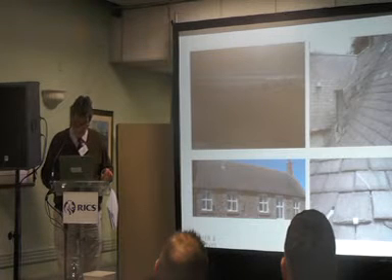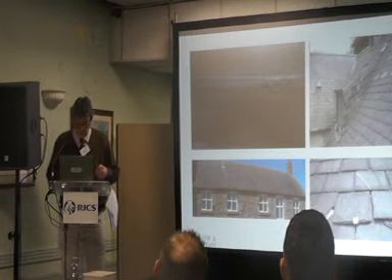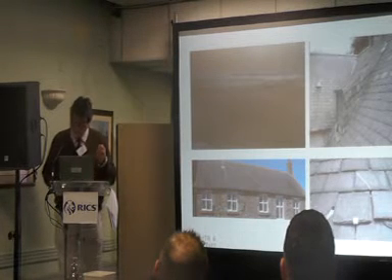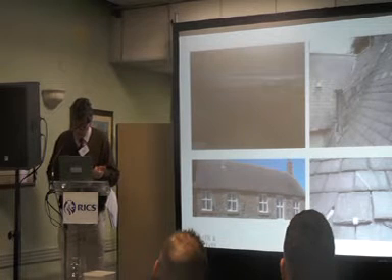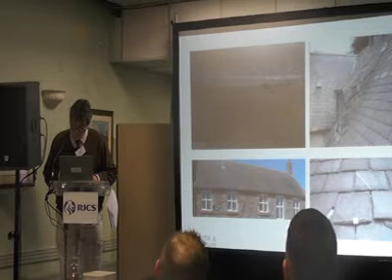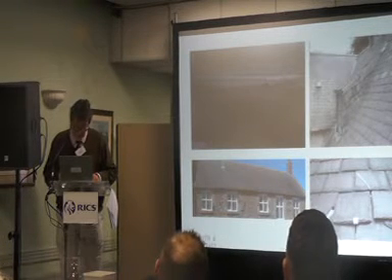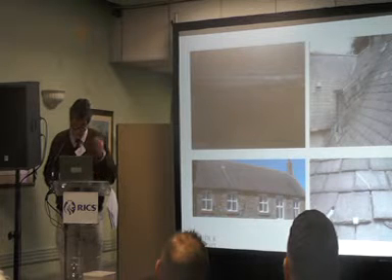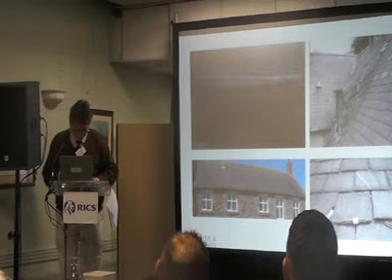When you look at a roof, you're not always going to be able to get close to it. You might need field glasses. You're looking for tingles, you're looking for wire tingles. Sometimes you're looking for copper wire tingles. Sometimes you're looking for hooks. And they're all clues that you've got probably nail failure, sometimes crumbling slate where a nail hole just pulls to the edge.